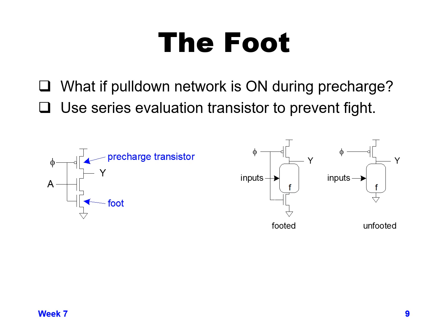And an unfooted domino is one where we don't have a series device that's being clocked in series with the functional logic of the NMOS tree. That is an unfooted, and typically I'll call that a D2 type domino stage. So D1 is the first domino stage that you might hit, and D2 we'll see where the footed and unfooted can be used in conjunction with each other in future slides.